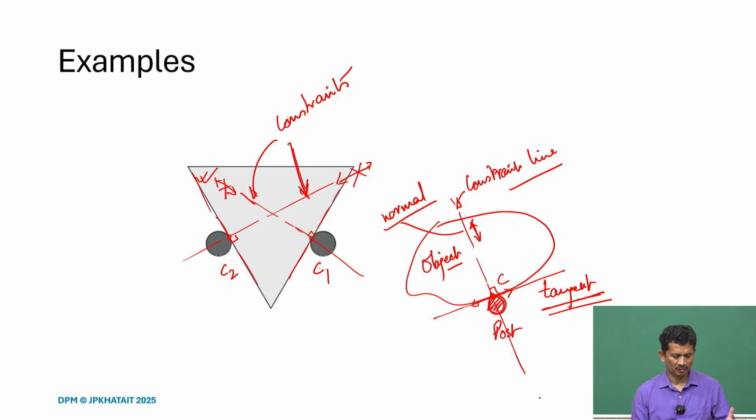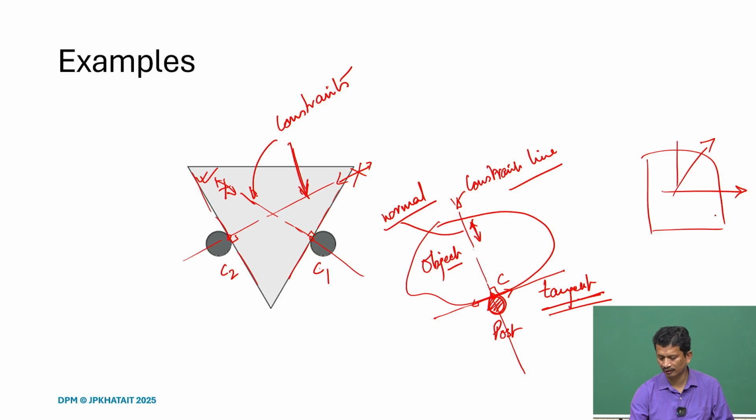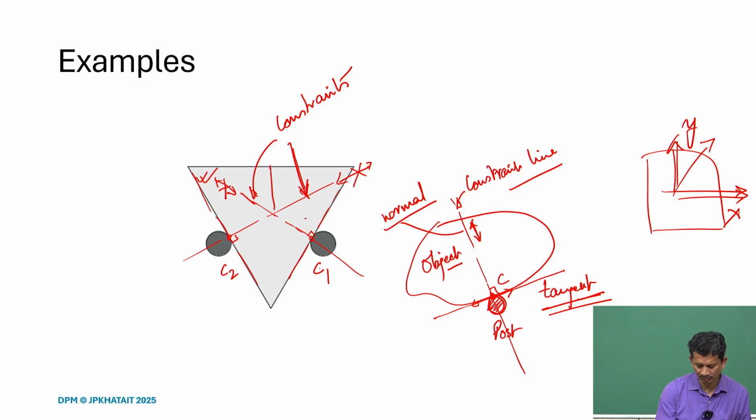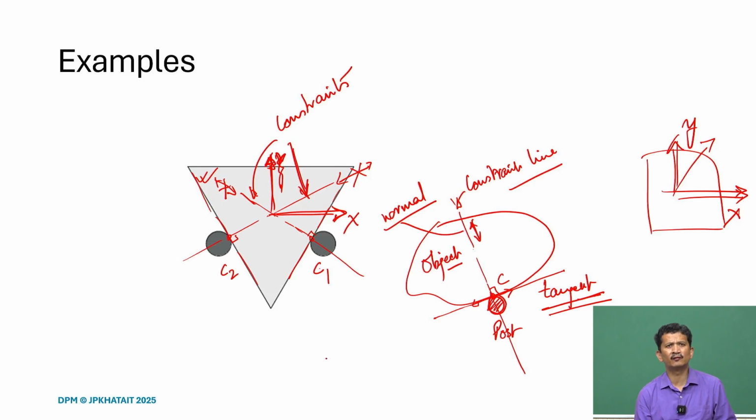So, it means in any plane, if any two motions are not possible, we can always find that it is not possible to move in the two perpendicular directions. So, call it x y. It cannot move along x and y directions. So, suppose I define a coordinate system x and y here, we can always resolve and say that the translation along x and translation along y is now restricted. Of course, what we assume is that there is enough nesting force in this case, so that the contact is always there.